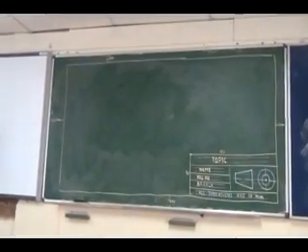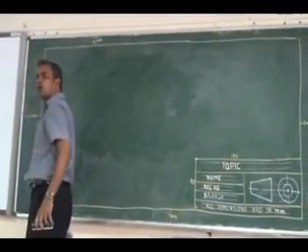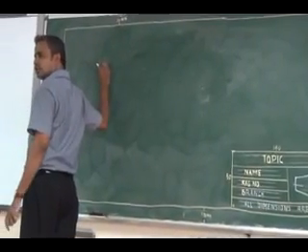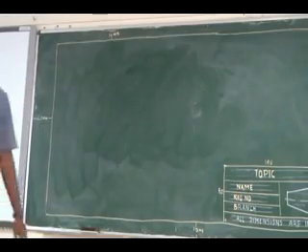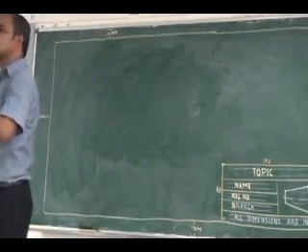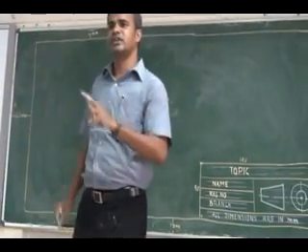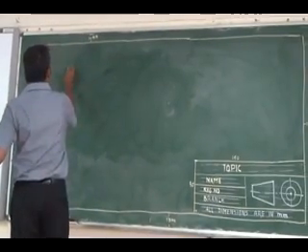Lettering: whatever you are going to write inside the drawing sheet or in a title block, for any writing you are doing in a drawing sheet, you have to draw two parallel lines, and I told you to maintain a 5 mm height. Because if you have a 10 mm height, you are not able to write neatly inside it.